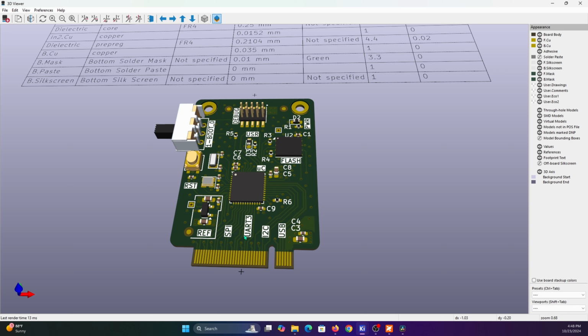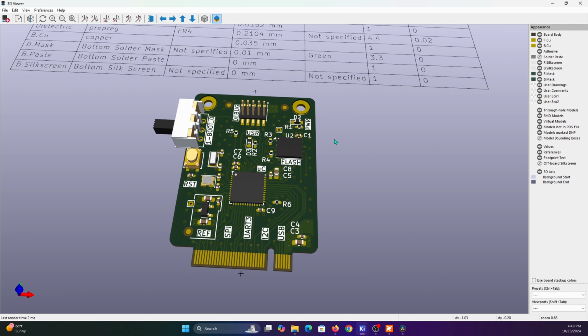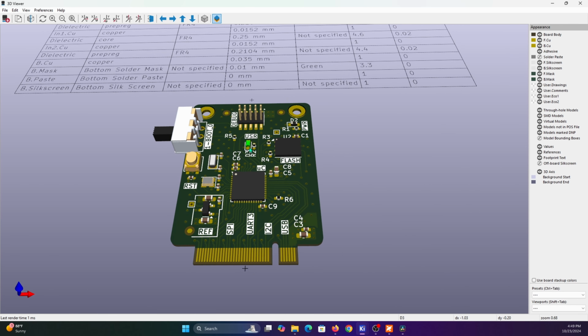Probably I'm going to start with UART, which is very simple, and using maybe the LEDs, to do our Hello World application, which is basically blinking an LED, and also how to program the board using the USB, just to test that the USB interface is actually working.